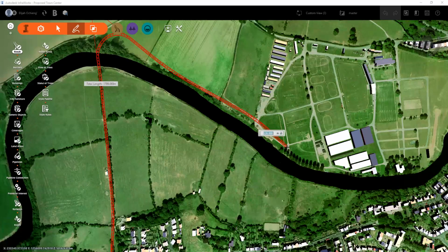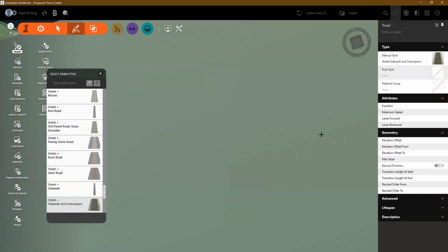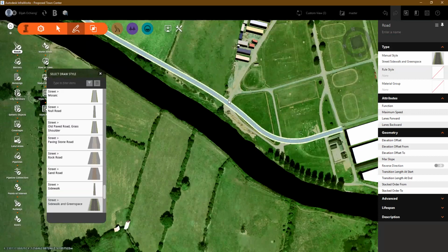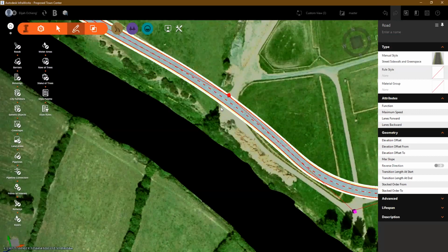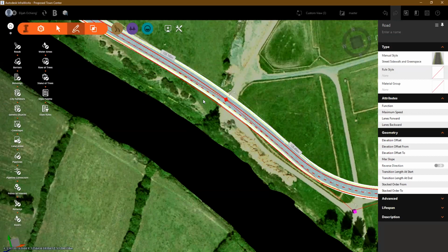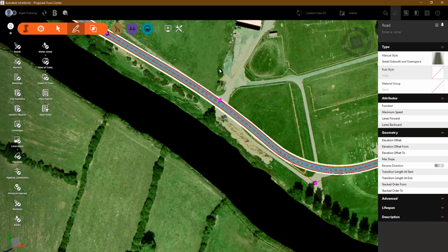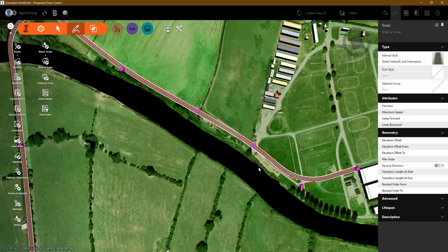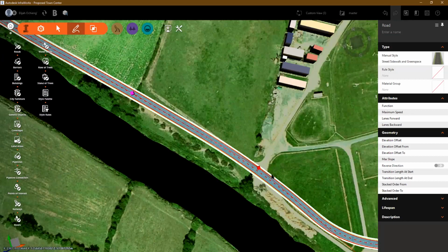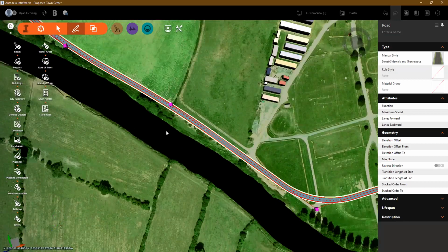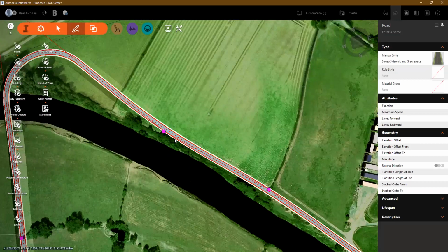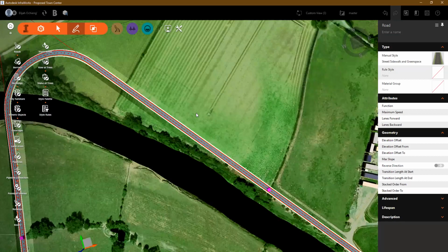So that's basically the process of laying out the roads using tools that InfraWorks provides us with. So I first lay it out as a sketch. Then after that, I can start adjusting to help me minimize the number of curves and tangent points along my road. Like in this case, I only want to have one straight point here. So I will remove this vertex here, and also this one here. So I remain with only one straight point plus one point of intersection along that road.